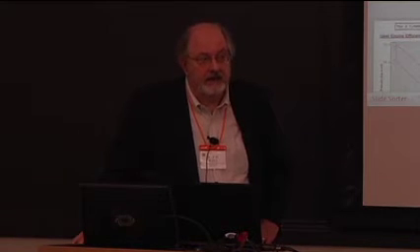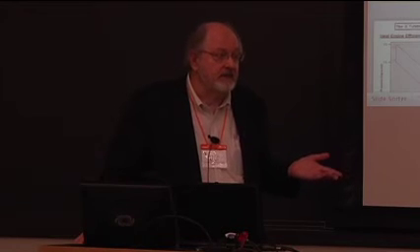Yes, that is a limit. And it's kind of like an upper limit. Although, if you take into account the full cycle with possibly using the exhaust energy in a turbocharger or maybe even other devices where you recoup some of that exhaust energy, then you've gone beyond that limit in a sense because you now have another way of using the available energy. So it may be a limit for the combustion process, but not for the whole system. All right?